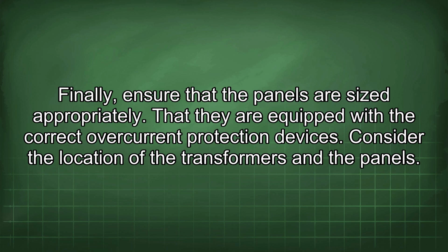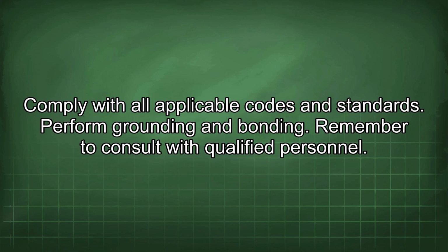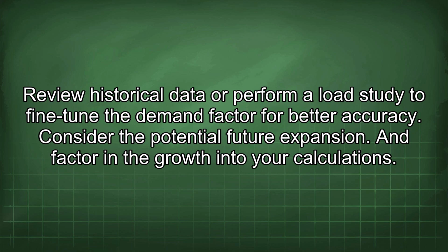Consider the location of the transformers and the panels. Comply with all applicable codes and standards. Perform grounding and bonding. Remember to consult with qualified personnel. Review historical data or perform a load study to fine-tune the demand factor for better accuracy. Consider the potential future expansion and factor the growth into your calculations.